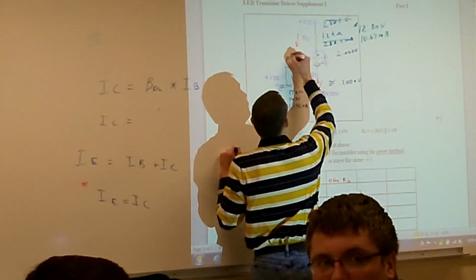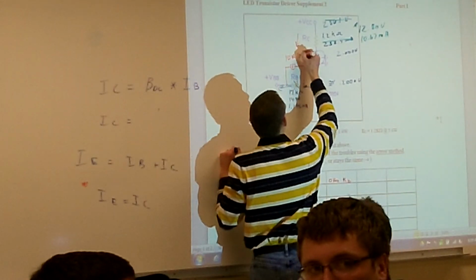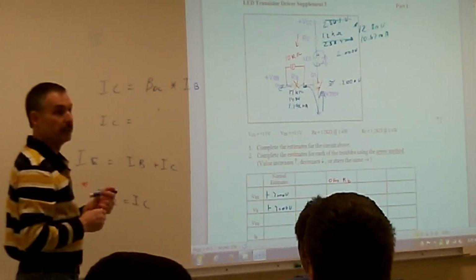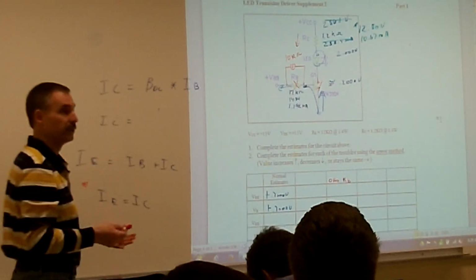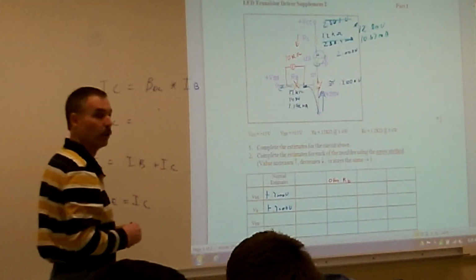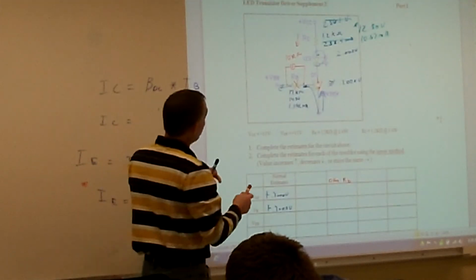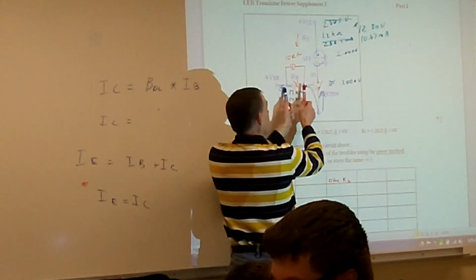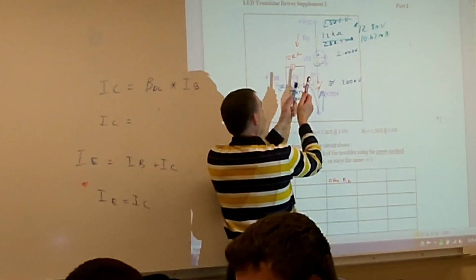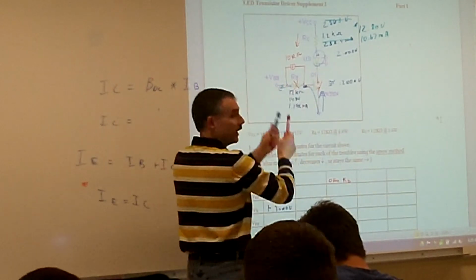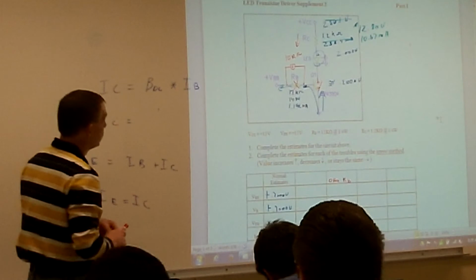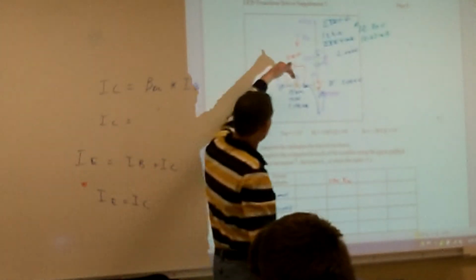Yep. Now this voltmeter is 10 megohms. I might not put it into saturation, so that LED might just turn on a little bit dim. Sometimes we have to look for it. Remember, I talked about digital circuits. All of a sudden, I'm doing some troubleshooting and I put my voltmeter across something, and I can turn that whole circuit on just by putting my voltmeter in there, because that voltmeter has some resistance. So we do have to be careful of that.